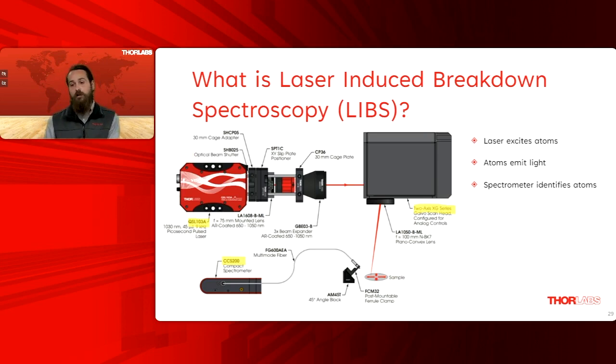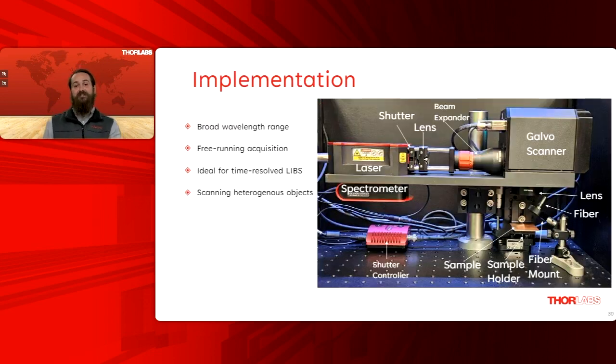Now, instead of caring about the removal of material, what we're going to do in LIBS is capture that plasma light and analyze the wavelengths coming off the plasma. By doing that, we can determine the elements that made up the sample we were just ablating. That's a very interesting application, almost forensic it feels sometimes. You can take an unknown material, zap it with a laser, and simply by looking at the plasma that comes off of it, determine what it was that you just zapped.